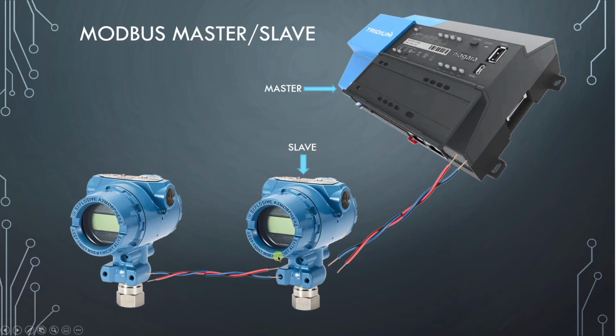Now, we saw this controller being a master talking to this slave. Now, what happens between these two when it communicates? If you have a query coming from here and you want to bring it to this device, you send it to the first device as a master, or the protocol analyzes that the slave is after another slave, so this becomes a master and sends it to this slave.